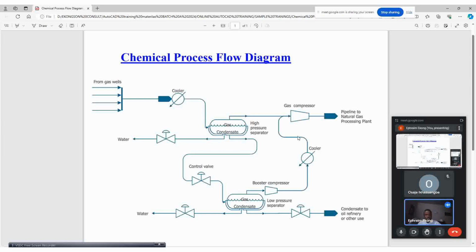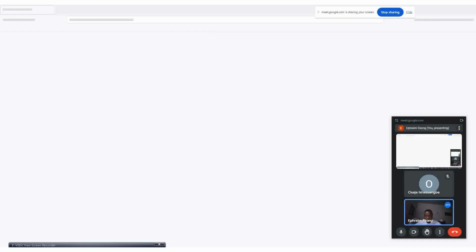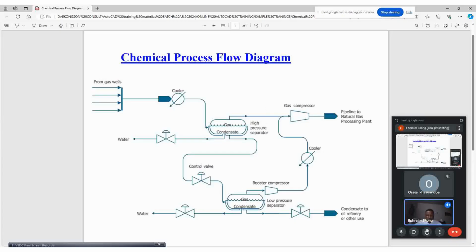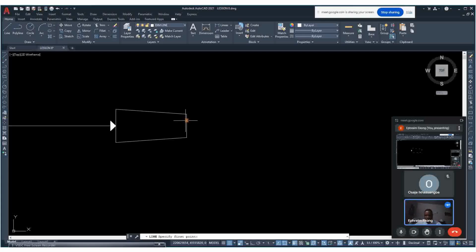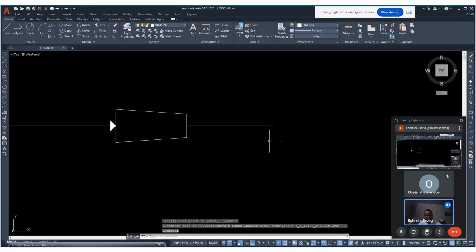So there it is. Okay, so what next? We have to achieve this as well. I've gotten it already. Just pick a line. Click, locate the midpoints, anywhere you see a small red rectangle. That is the midpoint. You click and ensure auto is on. Take it this way and you click OK and press the escape key to end your command.